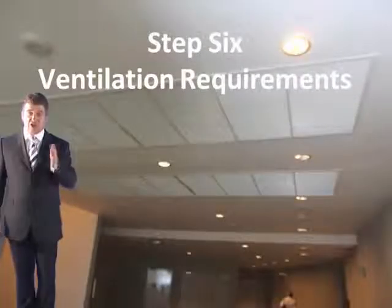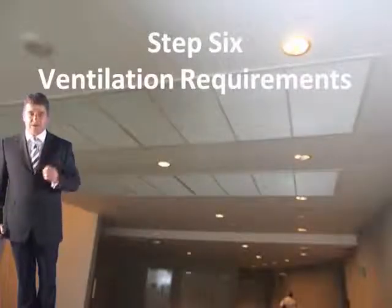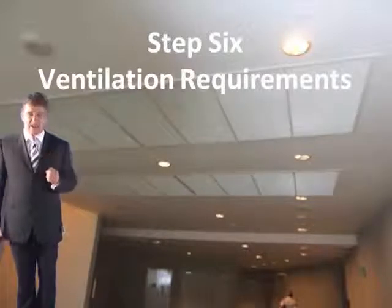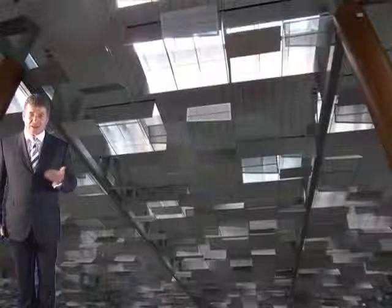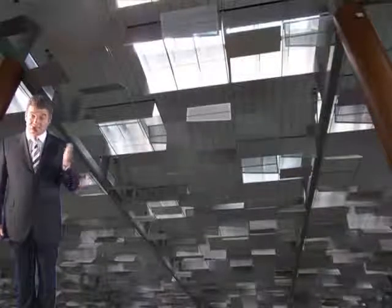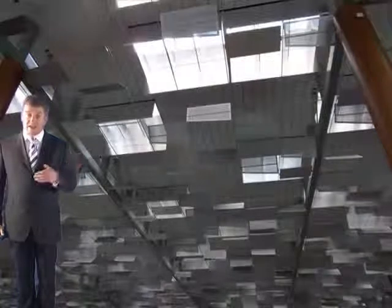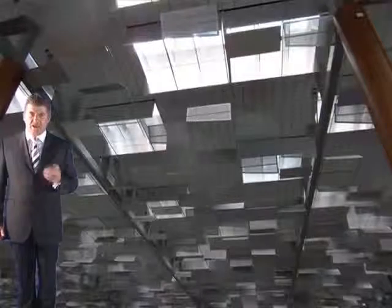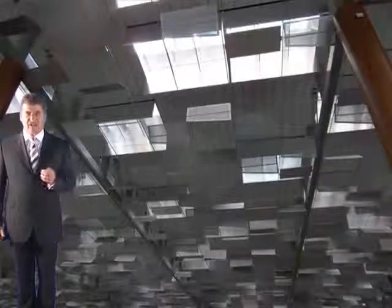So let's move on to step 6 now, which is determining the ventilation requirements. Now you've got a couple of choices here. You can go for natural or mechanical ventilation. Generally natural ventilation is preferred mainly due to cost implications, and that is obviously if it's possible. And in this situation clearly it will be the initial option. Let's progress on the assumption that we're going to do natural ventilation.